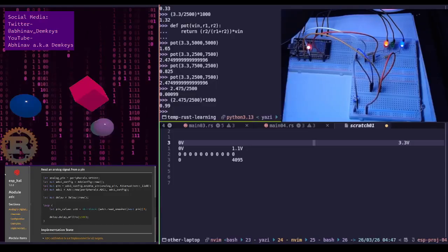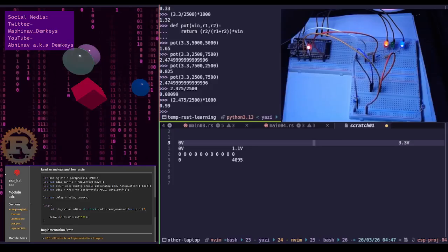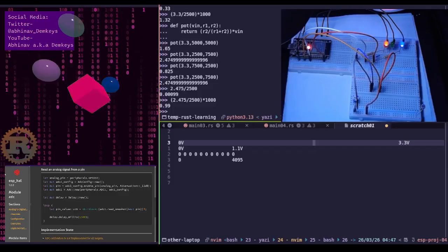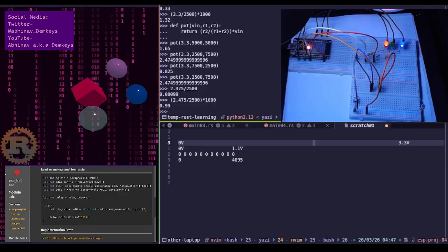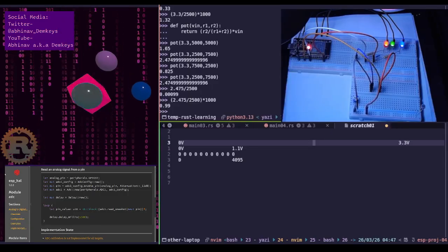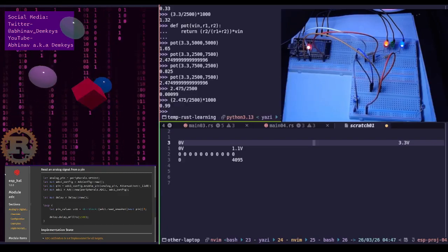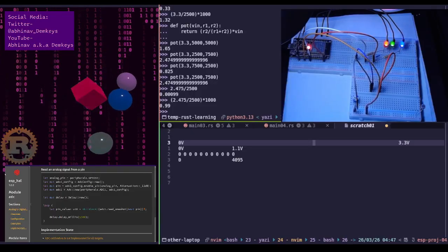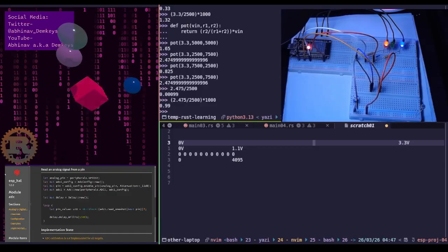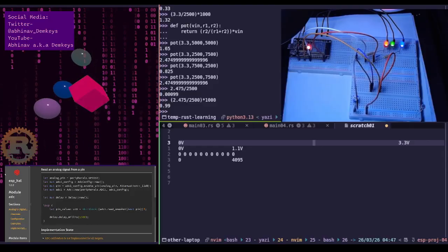physically when you keep turning the thing, let's say you're at the low end and you've set 0.5 volts to be your starting point, right? You're going to have to turn the knob a little bit with just nothing happening, no response, until you hit 0.5 volts. So that becomes the dead zone. You still have to turn within that dead zone, and then you have that awkward kind of thing going on. It's going to be a little more accurate though, that's for sure. It's going to be accurately mapped from the range that is actually working to another range that's actually working.